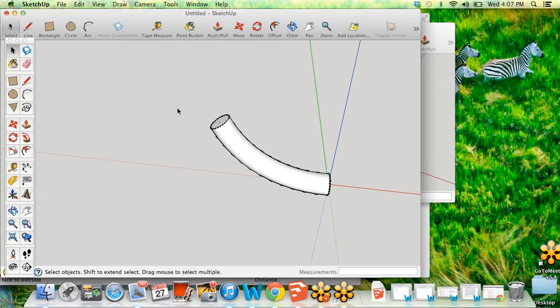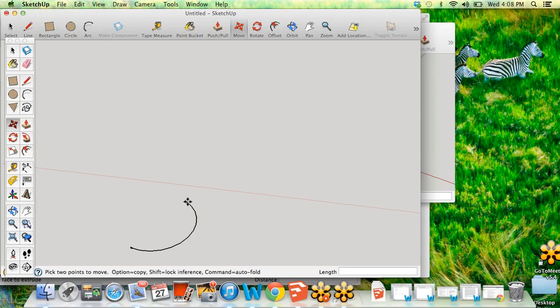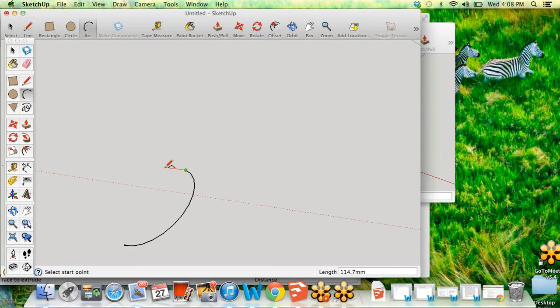One cool thing that you guys can work on, that could be difficult, if you wanted to make almost like a tube slide, remember that you can create tangents that make almost like a curlicue. So right now I am creating this, I created that tangent flat on the ground. I moved one endpoint up, and I could keep doing that. I could do that again. Oops.